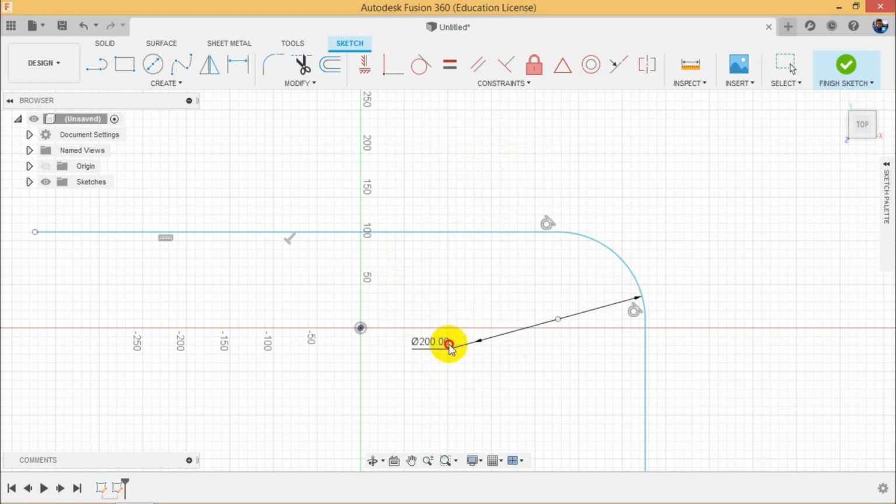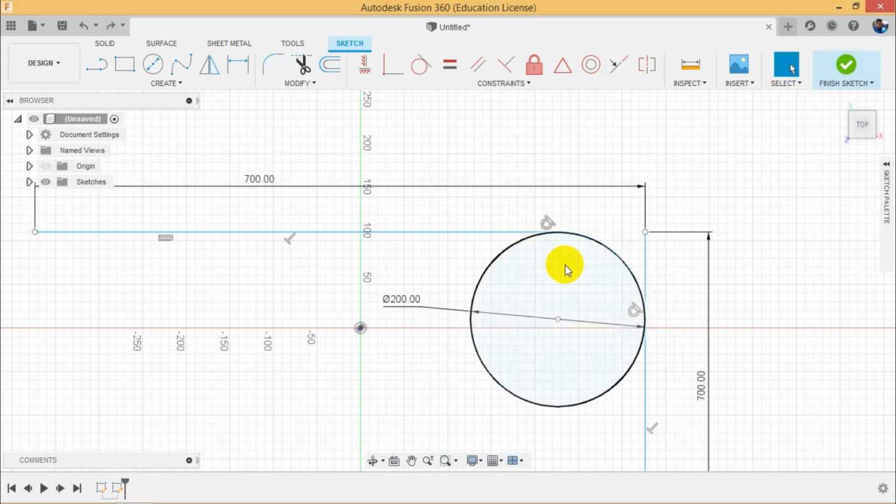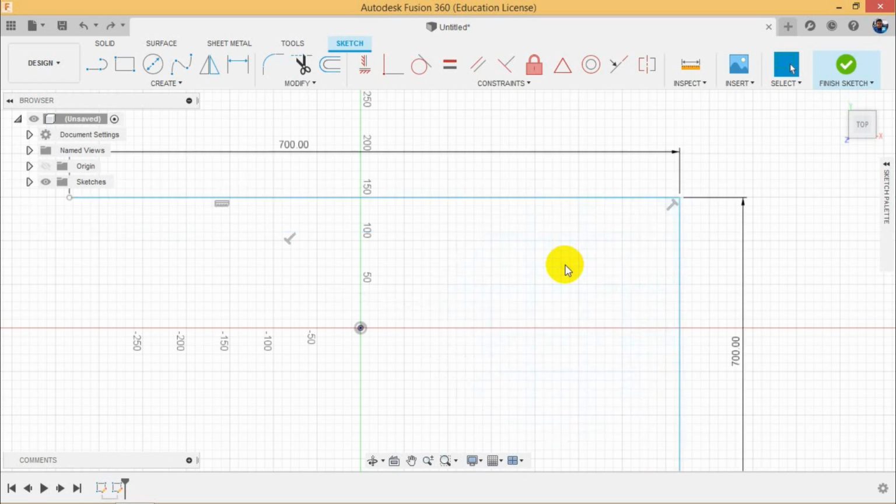So this arc radius is 100, right? So 100 radius, and this element will be called a 100 radius fillet that will be sweeping smoothly tangentially from one line to another. So you can create this in an easy manner. How can you create it? I'm pressing Ctrl Z and going back to the primary shape. This was our primary shape, right? So I'm going to use fillet.